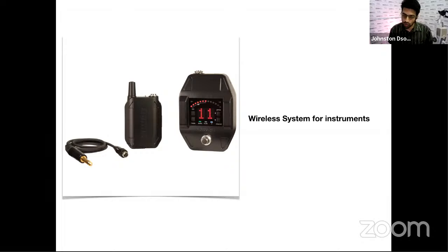So now you should know how to distinguish a transmitter from a receiver, because in many cases they look very, very similar. One example is here, both of these look very similar. An IEM transmitter and a microphone receiver will look very similar. So don't get confused between that. Don't get confused about where to connect your antenna. You need to know which antenna has to go where. You need to read on the device, and at the same time look at the connections on the device, and get to know which is a receiver and which is a transmitter.